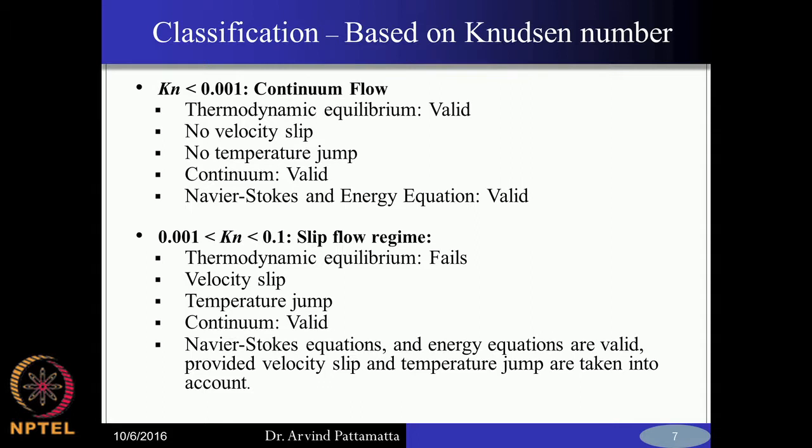Okay. Now, this can be accounted for at the walls by bringing in what are called slip effects. There are two kinds of slip, one for momentum and the other for energy. We will see in the next few slides how the slip boundary conditions come up, but you still solve your Navier-Stokes equations in the broad sense. Instead of a no-slip boundary condition, you account for the local non-equilibrium at the walls by means of the slip boundary condition.